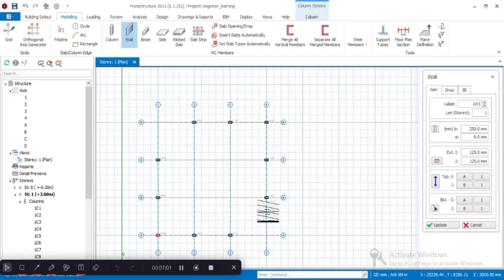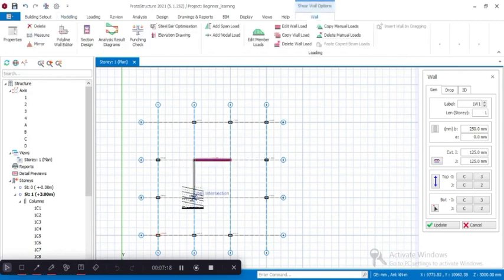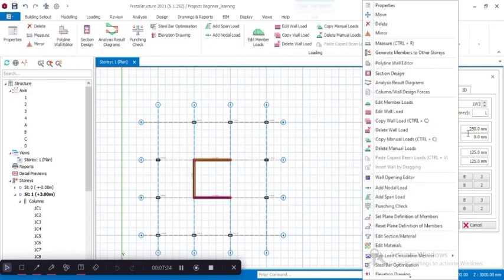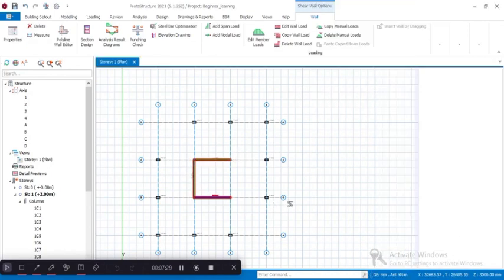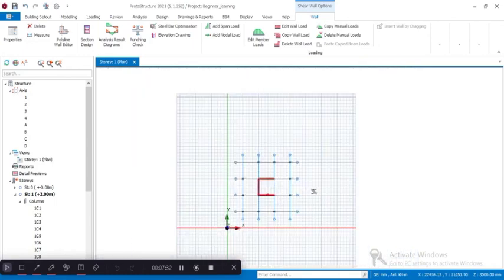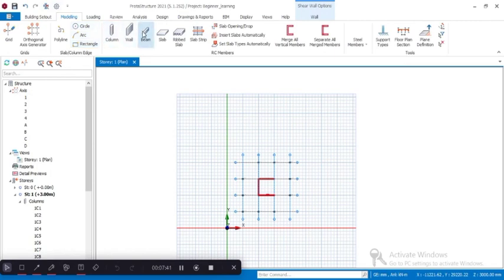So now there is a certain three numbers of wall. This is a reinforced wall. It's not just any wall. So there's brick wall, there's partition walls on Prota, and there's reinforced walls. So this is what we use for things like elevators and reinforcement, retaining walls. Sorry. So this is what is meant by that. We have inserted our three number walls. So these are our walls now inserted. Close. Then beam creation. We are going to be inserting our beams also. So we go back to our modeling beam.